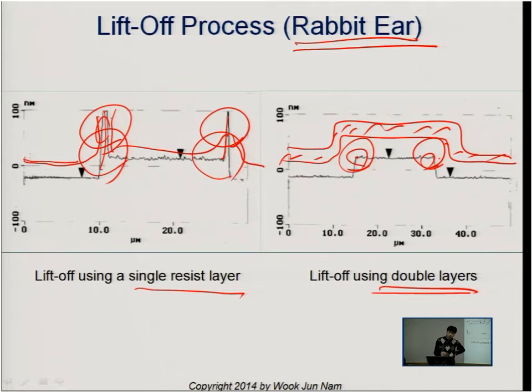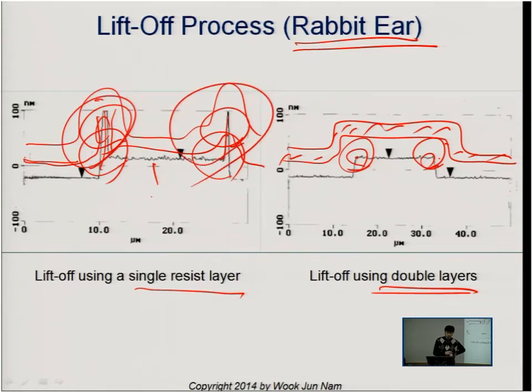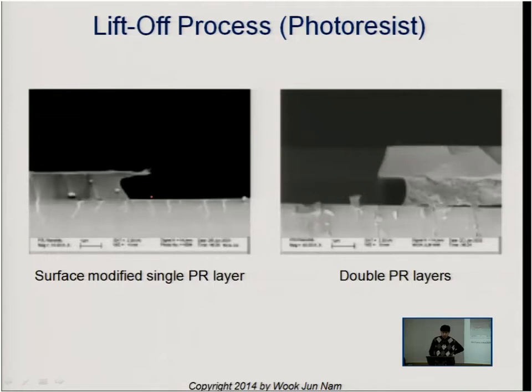it cannot conformally coat these vertical structures. And then when you put another metal layer on top, one metal layer and the other metal layer can easily short. So it can make a defect in your device. If you just deposit the electrodes and are not going to put any oxide layer, they should be okay, if we just measure the source and drain without any additional deposition. Right. So it depends.